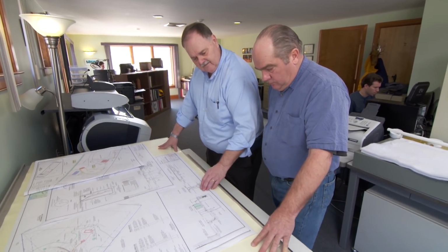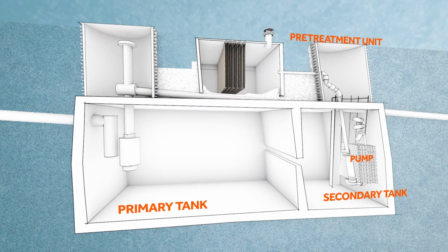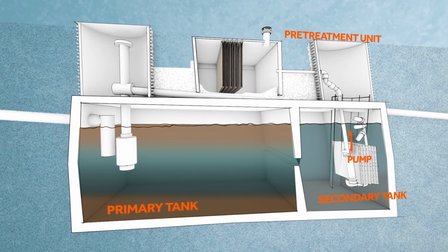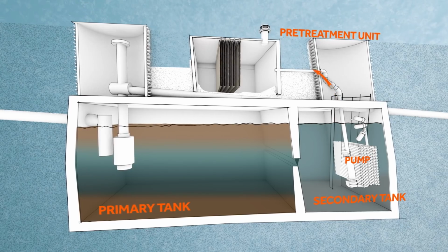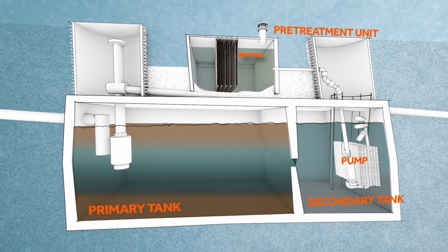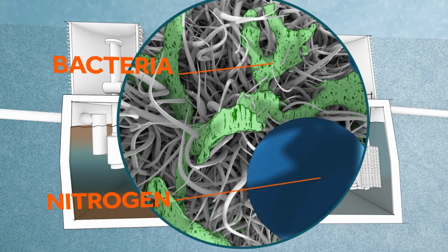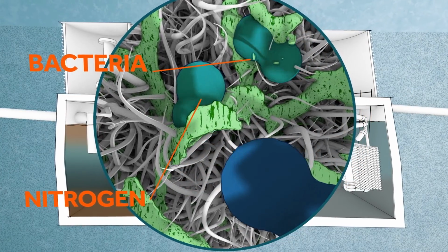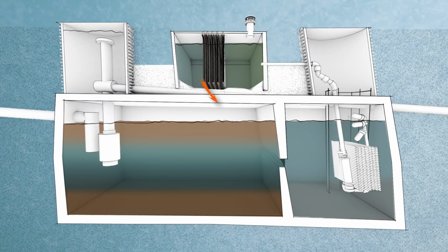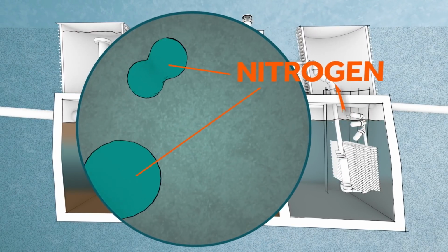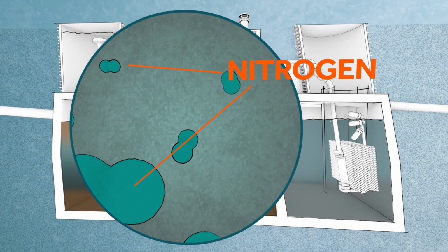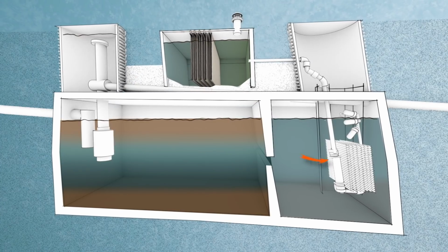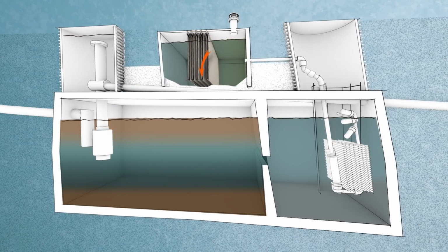Well, first off, we have the house here. We have a similar type septic system. Then it goes into this second baffle of the tank. It goes into a pump. It pumps up onto this Advantex pretreatment unit, which has hanging sheets in it full of bacteria. The bacteria change the type of nitrogen that's in the system. It flows down into this tank and where the actual denitrification takes place. So the denitrification takes place down in the septic tank. Mm-hmm. So it flows through here 3 to 4 times. At each cycle, only a portion of the flow goes out to the leach field.